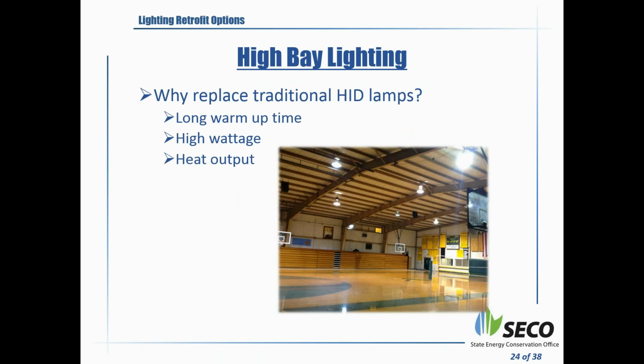The other application is high bay lighting. Why replace traditional HID lamps? Usually you will have HIDs in there, which are high intensity discharge lamps. Anybody who's installed them knows that once they're turned on, they stay on all day long, because if you turn them off, it takes 10 to 15 minutes to warm them up and get the same light levels you had before. As a result, you will see them on all day. They use higher wattage and they also generate a lot of heat.